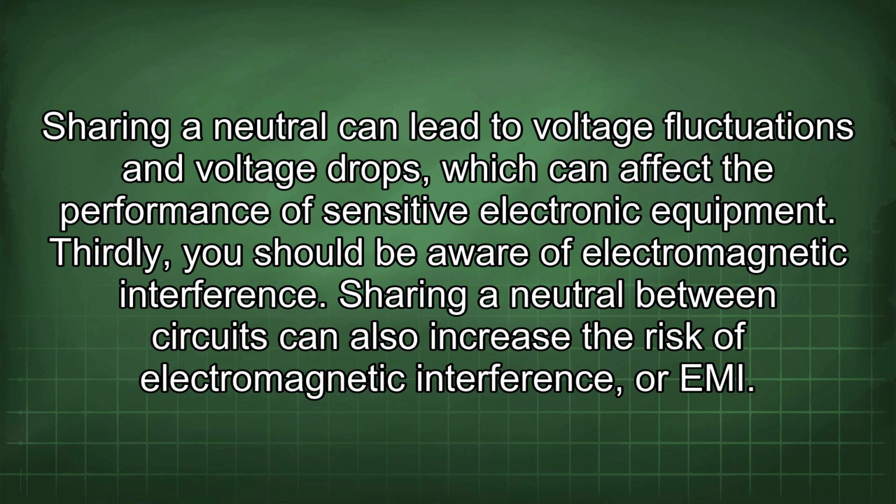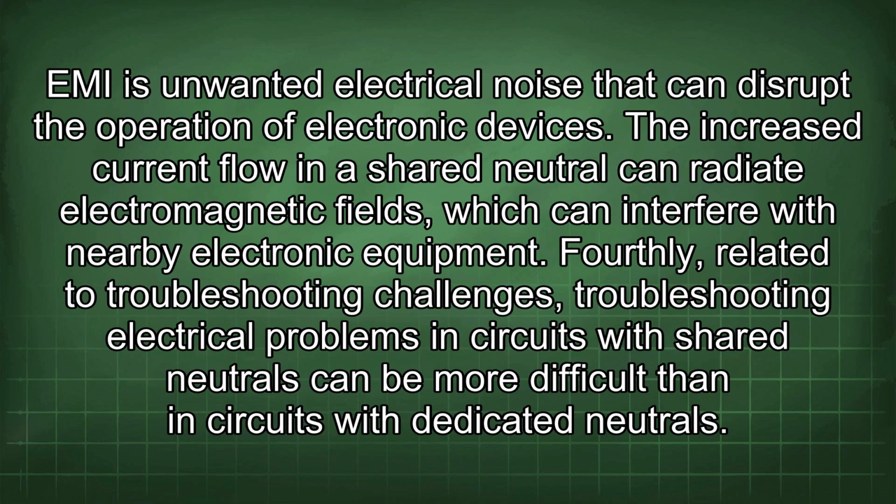Thirdly, you should be aware of electromagnetic interference. Sharing a neutral between circuits can also increase the risk of electromagnetic interference, or EMI. EMI is unwanted electrical noise that can disrupt the operation of electronic devices. The increased current flow in a shared neutral can radiate electromagnetic fields, which can interfere with nearby electronic equipment.